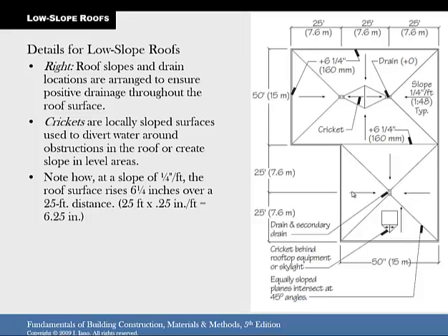And it says on C, if the roof edge can rise as much as 16 inches above the drain level, what is the maximum possible slope? So first you figure out what it is at 1/4 inch per foot. Then you go back and say, okay, this is going to be 16 inches above, and you go backwards and see what's the biggest slope you can get. So try to do that first.